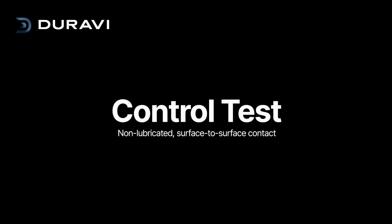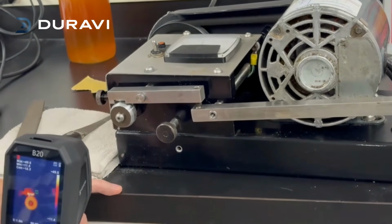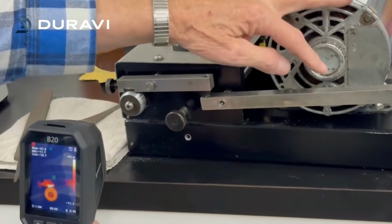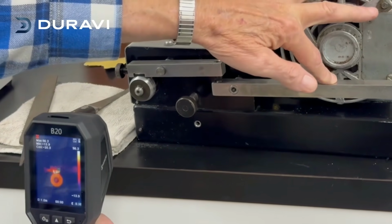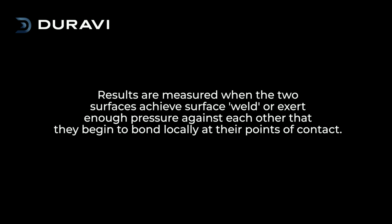Stage 1, control test, non-lubricated, surface-to-surface contact. Everybody see where that's at? You see the heat on that surface. As I apply it, what happens? Goes right up to weld. Results are measured when the two surfaces achieve surface weld or exert enough pressure against each other that they begin to bond locally at their points of contact.